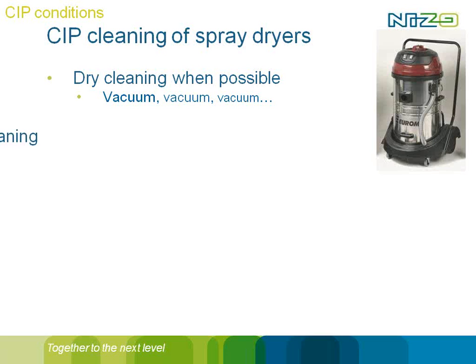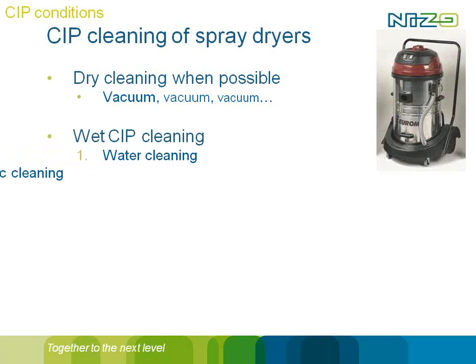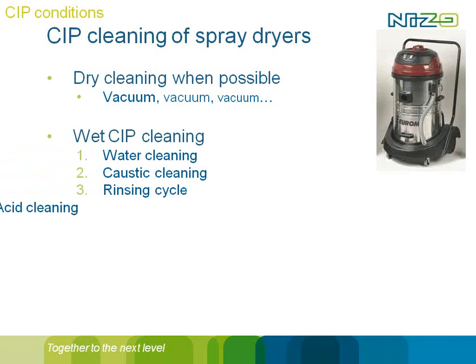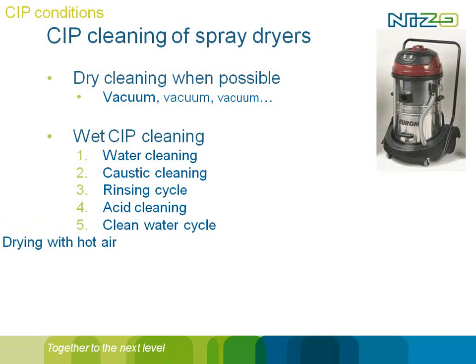If you do have to clean wet, and in some cases the type of tower, the cleaning tower, makes it necessary to do so, actually the way of cleaning is not different from a standard CIP procedure. But what's very important is that you do have step 6, which is drying with hot air. It's very important to get rid of all the water remainings in your production process, because the combination of dry powder with water will always result in extra contamination,